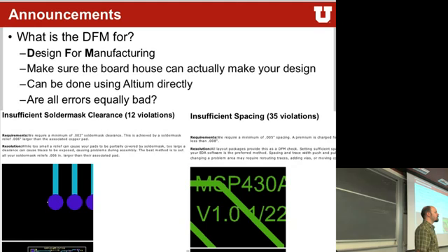Did you reduce that, or did you set it to 0 mil expansion to avoid solder mask slivers? Probably. What can happen is if you actually make an expansion, it expands so much that there is no solder mask in between these two pads anymore. And then it becomes more difficult again to solder, because you can bridge these two pads. You can imagine, if you look at the PCB, if these two coppers are so close together and there is no filling in between, it's very easy for solder to go in here and bridge these two. But if there is solder mask in between, bridging is avoided more often than not.